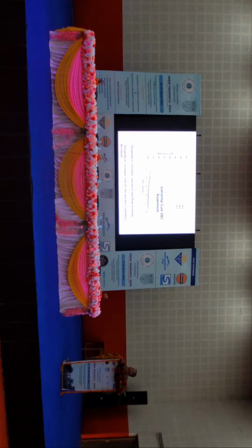Next one, please. So I conducted it, and within 30 minutes the complete reaction was completed. You can understand that as the curing temperature increases, the maximum heat flow increases, and when the temperature increases, the time for the reaction decreases. Next one, please. Obviously, from the heat flow curve, partial heat by total heat gives the degree of cure. This is the degree of cure for 50, 60, and 70 degrees centigrade. Next one, please. Again I have differentiated the degree of cure curve and obtained the rate of degree of cure curve for different temperatures.